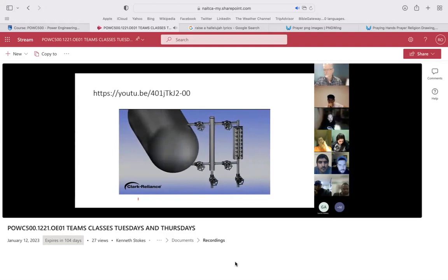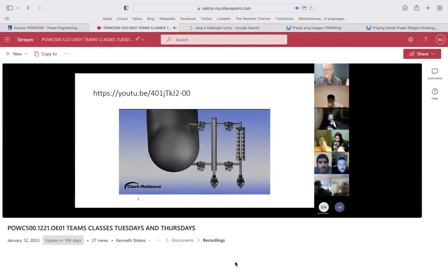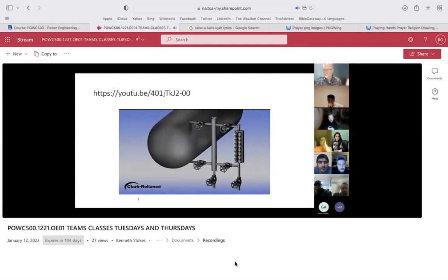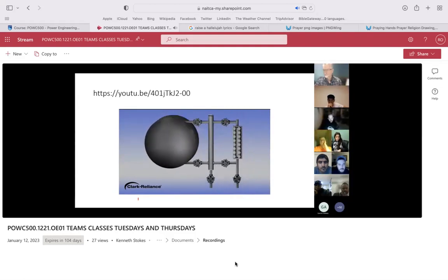We will now describe the recommended procedure for blowing down water level indicating instruments on a power boiler that's been constructed to meet the requirements of the ASME Boiler and Pressure Vessel Code. Please note, isolation valves between the drum and the water column, number 1 and number 3, are optional by code. However, if they are installed, they must be locked open under normal operating conditions.